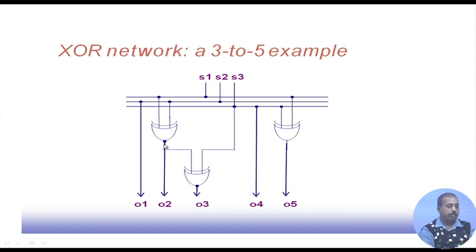This is done by means of the Gaussian elimination process to find, for a particular test pattern, what the seed value should be. That is obtained, and then that seed value is fed from the ATE, and this decompressor calculates the pattern that will be fed to the circuit for testing.